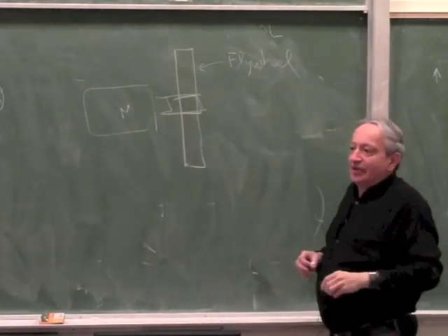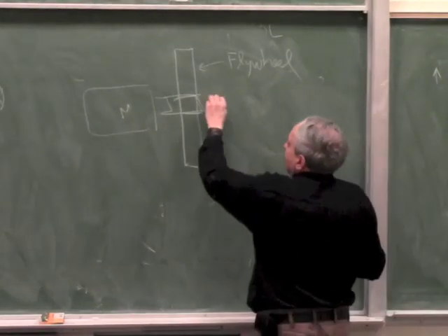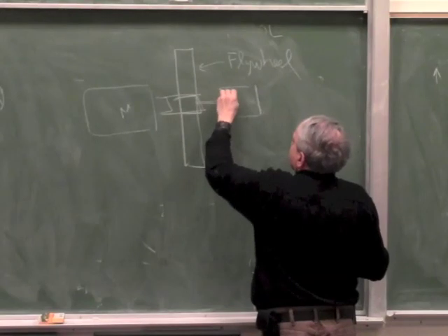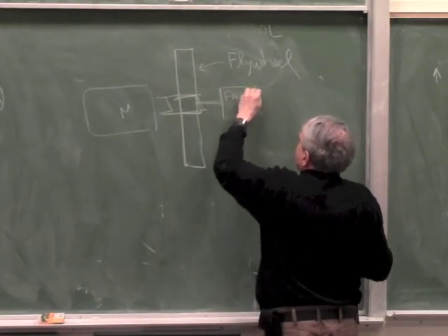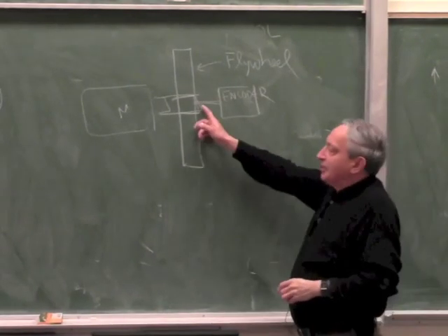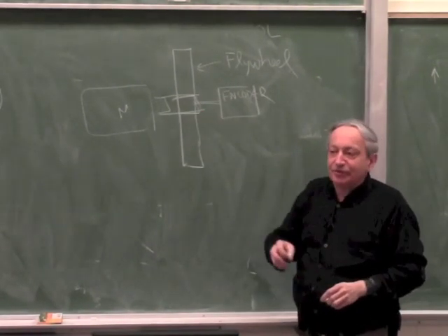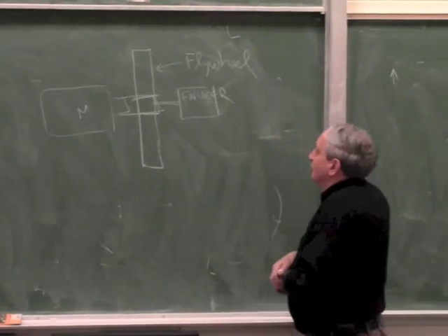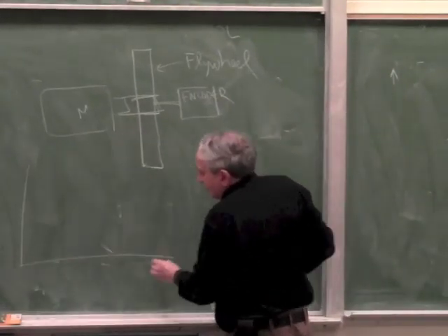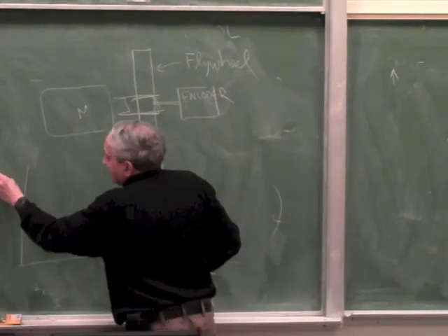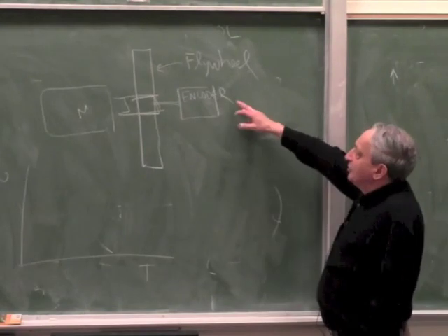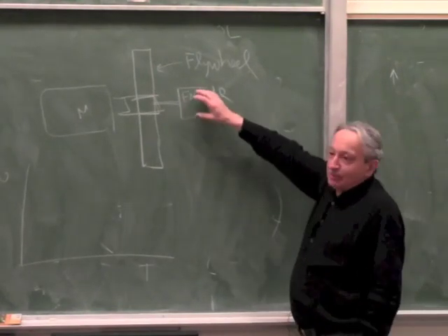And all what you do is you take a shaft encoder, or if you don't have an encoder, just even an optical switch which gives you 1 pulse per revolution. Okay, so you want to plot omega versus torque.